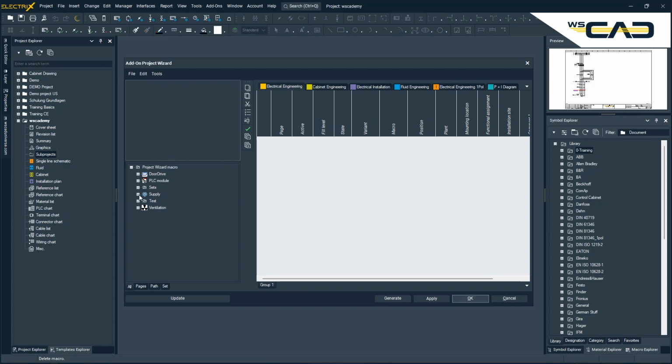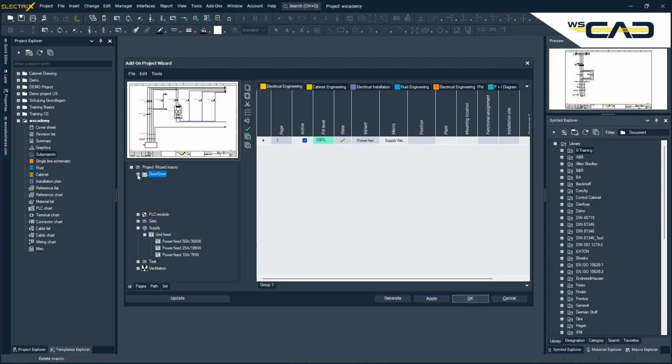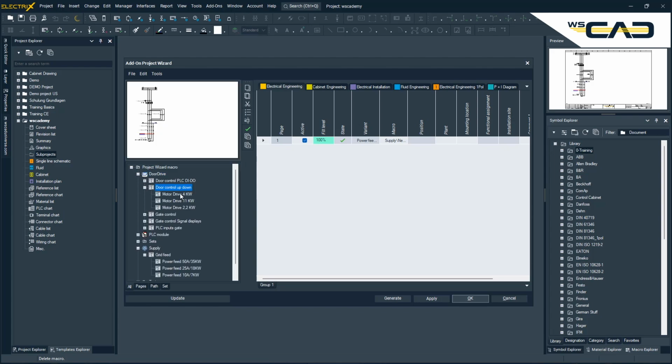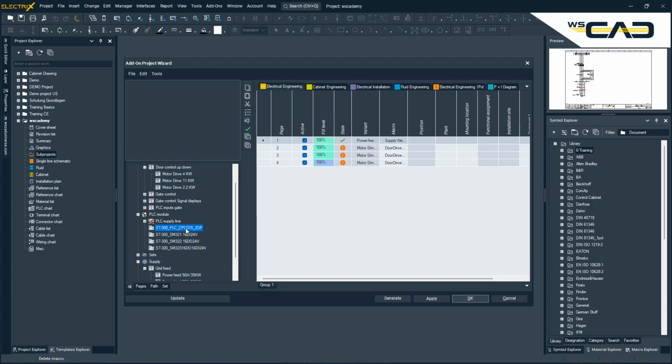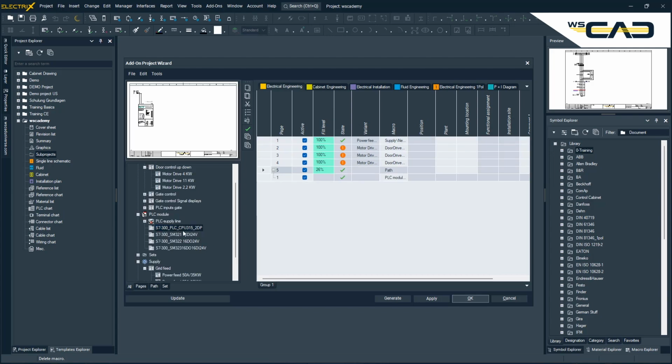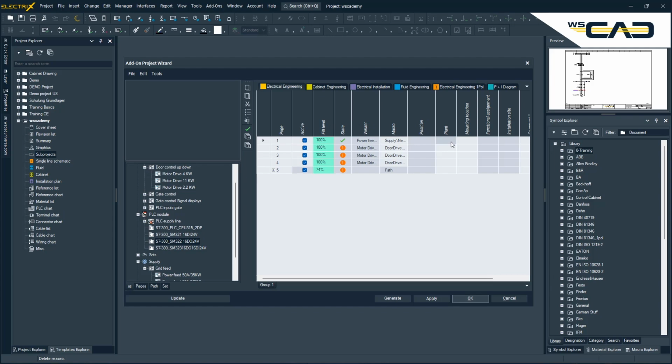As in the circuit diagram, a high degree of standardization is also required here. However, let's now simply select a feed in the circuit diagram, add a few more door operators. For a door up-down movement, add a PLC, start with a CPU, and simply add an input and an output card to this CPU, and you already have a small configuration ready.